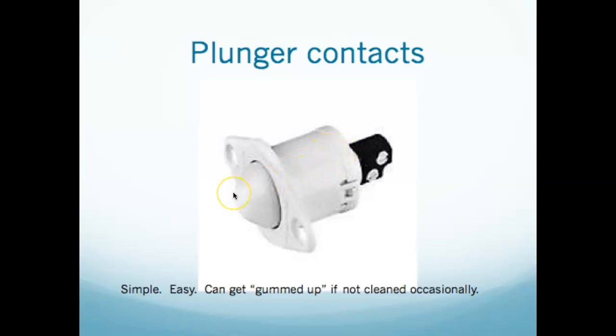And when the plunger comes out, when whatever is holding this back, could be on a drawer. These are used on metal drawers. If you want to alarm a file cabinet, a sensitive information file cabinet, you could put one inside. And when the door is closed, the metal lip pushes this back in, keeps these contacts together, and it says the door is secure. And when somebody pulls the drawer open, this stays on the file cabinet frame itself.